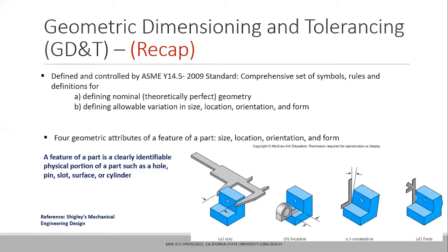So the designer has to make a trade-off between the functionality of the parts being fabricated and making sure that the manufacturing cost and the quality control cost, because of the inspection of dimensions and other details, are not exorbitantly high. To make sure the part is manufacturable and within the specific budget, we also have to make sure it has the necessary tolerances, not only tolerances but also necessary form and orientation control. Do you see what I'm saying, guys?